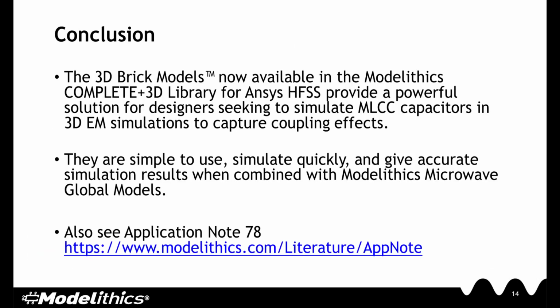In conclusion, the 3D brick models are now available as part of the Modelithics Complete plus 3D library for ANSYS HFSS, and they provide a powerful solution for designers who are seeking to simulate MLCC capacitors in their 3D EM simulations to capture coupling effects. They are not only simple to use, but they simulate quickly and give accurate simulation results when combined with Modelithics microwave global models.